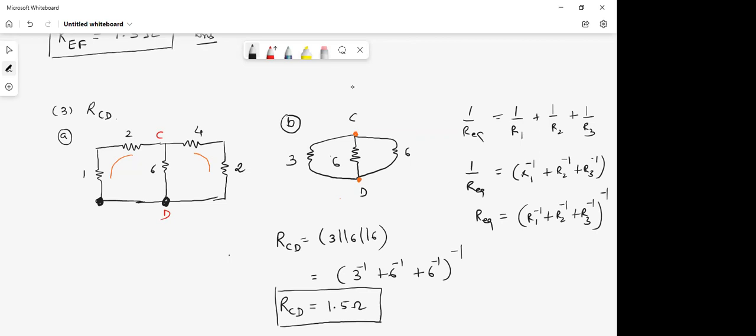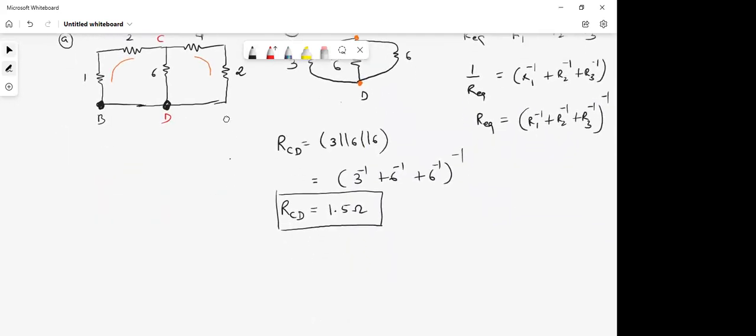So they are supposed to be considered exactly the same. Means you can always club these 2 points. These 2 points, say B and D, can be clubbed together. Just keep this concept in your mind. So if you were asked to calculate resistance between A and B, it will be the same as A and D, because whether you take point B or point D, since they are shorted, electrically they are the same.